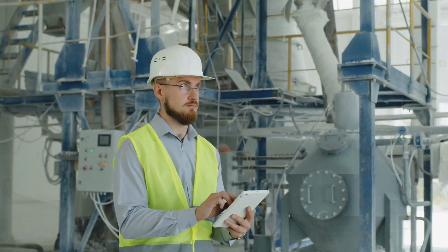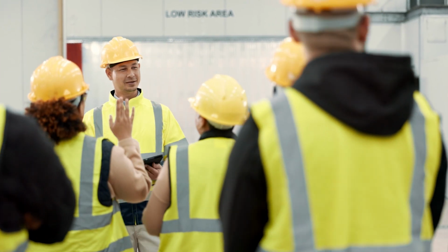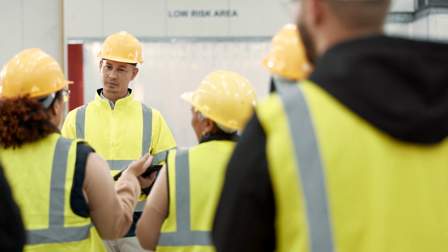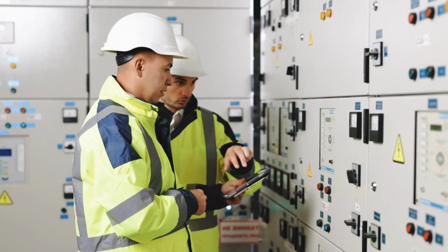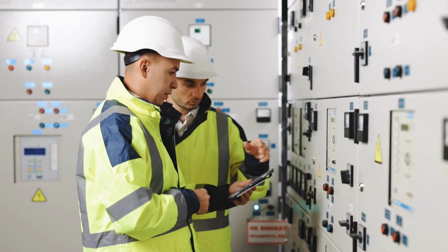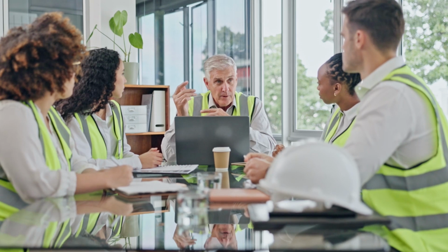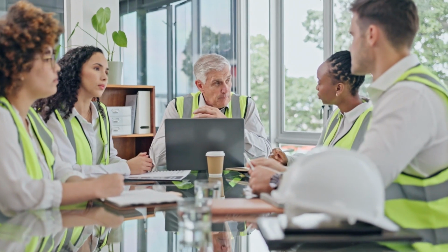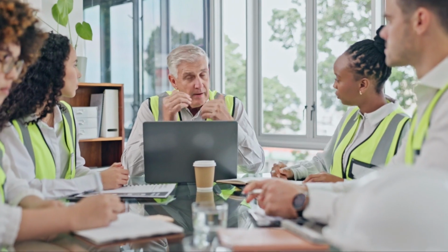As helpful as it is to identify hazards and analyze processes, it won't make much difference without a plan and procedure to transfer the safe practices to the employees who are dealing with the hazardous chemicals. That's why OSHA mandates that the employer develop and implement written operating procedures that align with the process safety information they compiled earlier. These must provide clear instructions on how to safely complete the activities involved in each process and must be communicated with the employees.